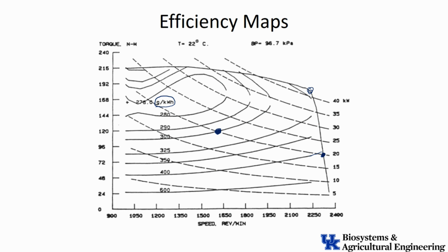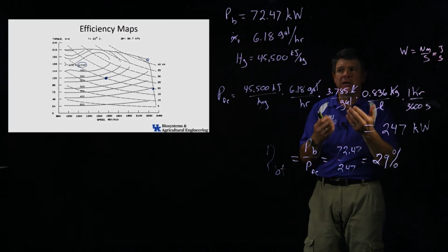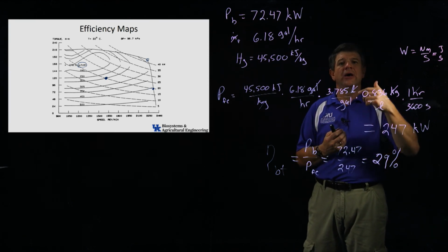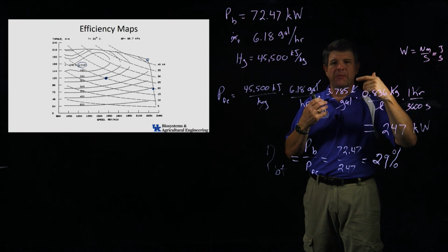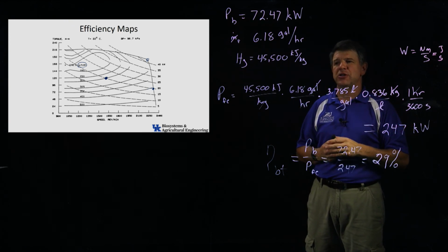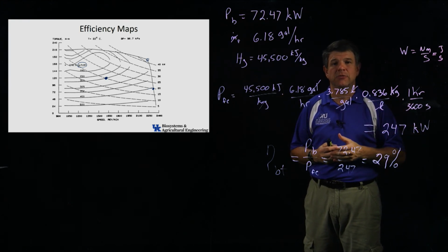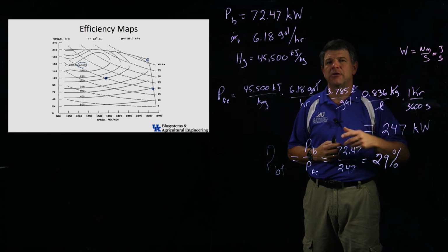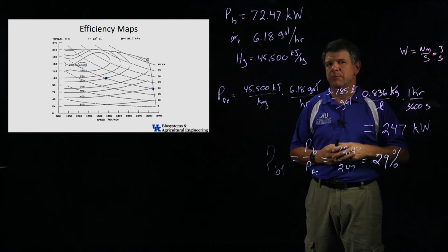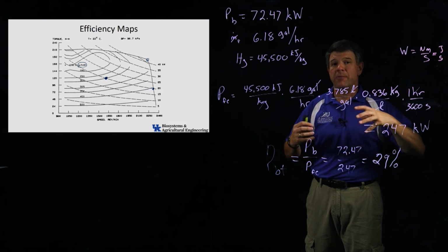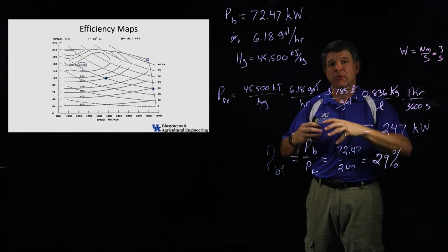And that's one of the things as we move forward in the industry is really looking at the electric drives and other things, because electric drives afford us the opportunity to slow that engine down. If I don't need all of the power out of that engine, I can actually slow that engine down a little bit, run it a little bit slower, and be able to get more efficient use out of it. If I need more power, then I can speed the engine up. The electric drives and the electric control systems in between will be able to compensate for all that. And so there's a lot of opportunities and a lot of growth that we're seeing in the machinery industry that way to try to become more efficient overall, not just making the engine more efficient, but to make the whole system more efficient.